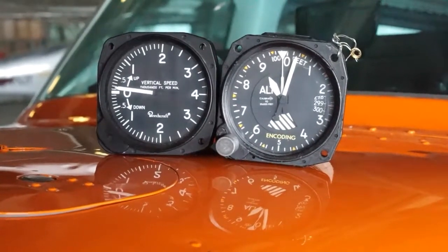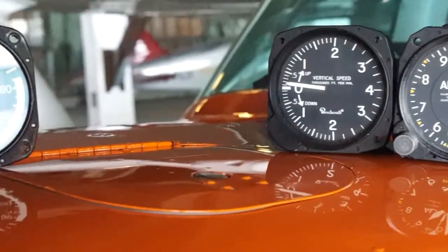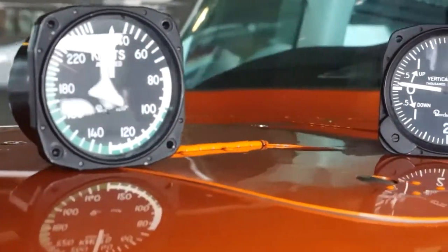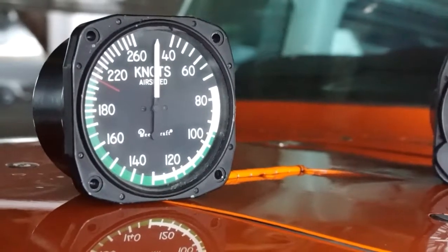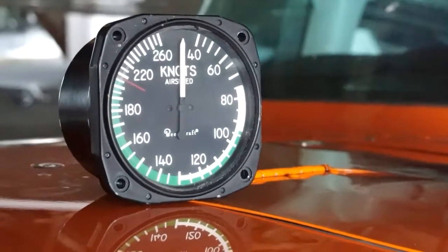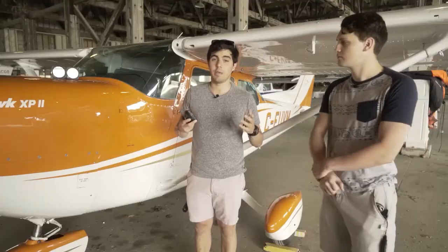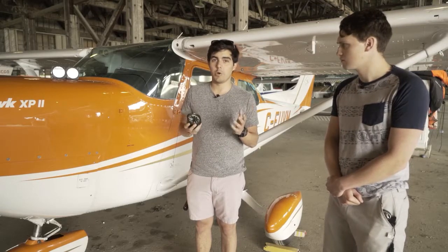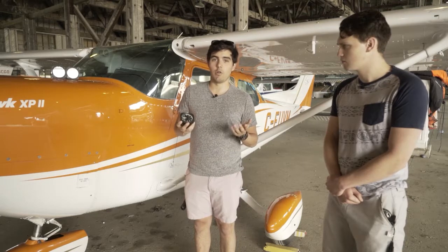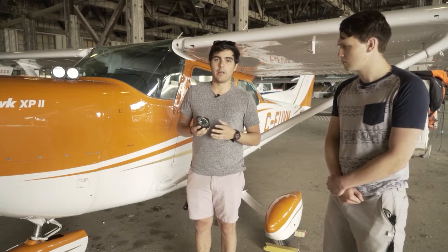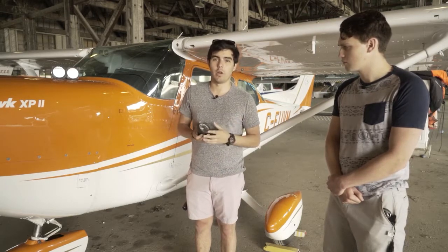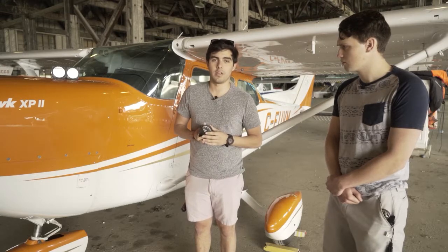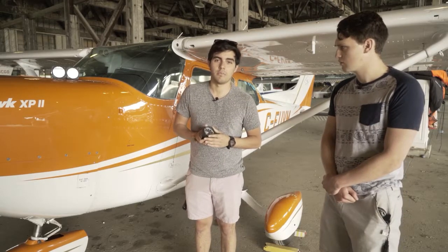And what these two probes in these three different instruments help you to basically gauge the performance of your airplane while you're flying. Now, you want to make sure that you know your airspeed, you know how fast you're climbing or descending, as well as how high you may be. If either of these probes fails, you could find yourself in trouble, given that a low speed would mean a higher stall probability, or a lower altitude would mean that you may find yourself in a dangerous situation.